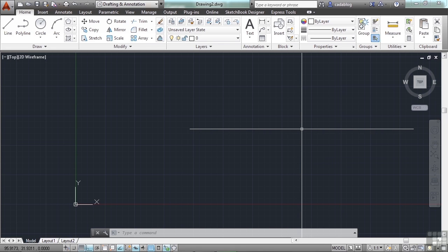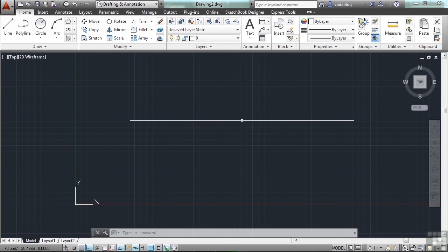Rectangles and ellipses are special forms of polygons in AutoCAD. Rectangles are fairly straightforward, where ellipses can be a bit tricky. But there are still a lot of things and a lot of ways that you can draw rectangles. Rectangles work a lot like the polygon command, except you're stuck with the criteria of a rectangle, only 4 sides. You get 2 parallel sets of sides that are equal. You get to pick 2 points on opposite sides of the rectangle to create your shape.